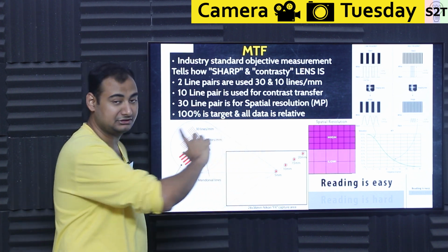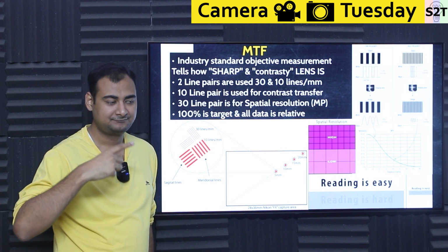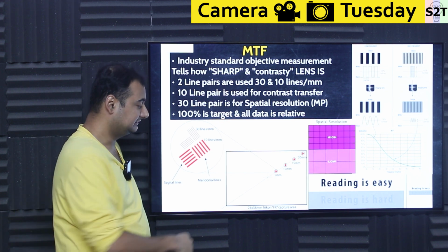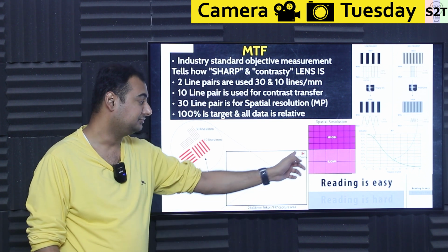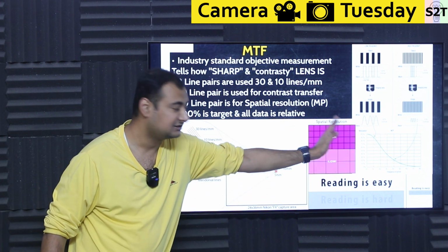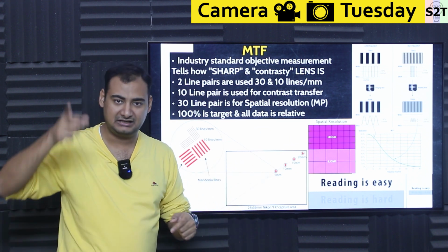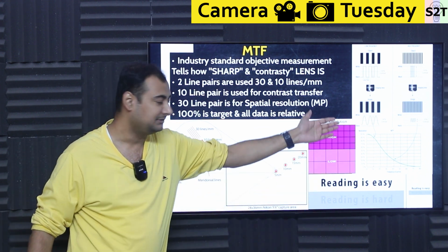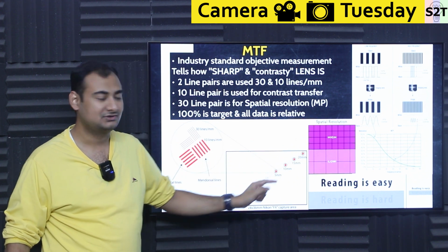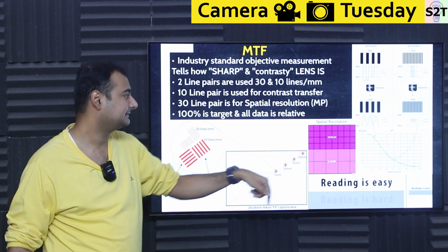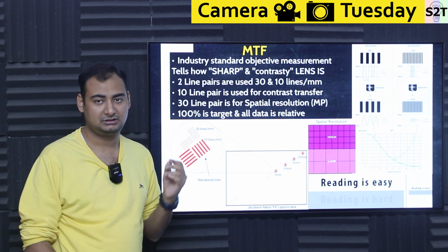If you look into Nikon, this is how they do it, and be mindful, lenses are always spherical, as in their projection area is round. They always take the diagonal of the sensor. So you will start from the center and then you go to the corner, and that's why MTF charts are always going like this. If they were directly shown from both sides, it would look like a bell curve, which would be redundant. So people came up with the idea of center to edge. That's it. And the edge is always diagonal like this because it has to go to the final corner of the pixels.